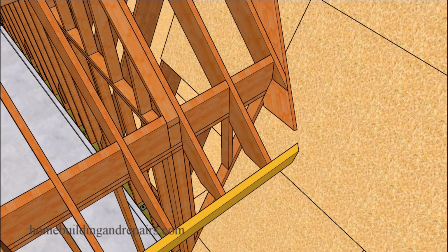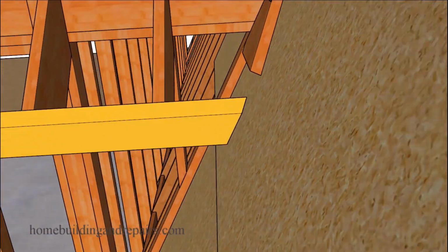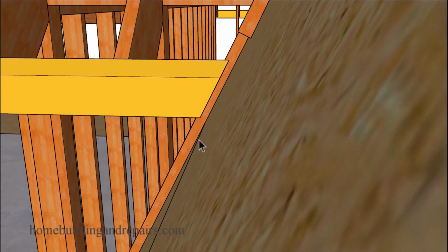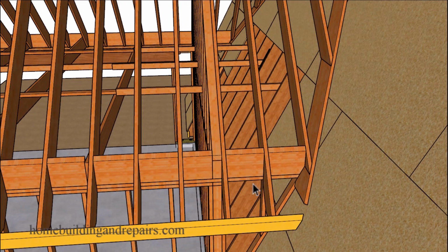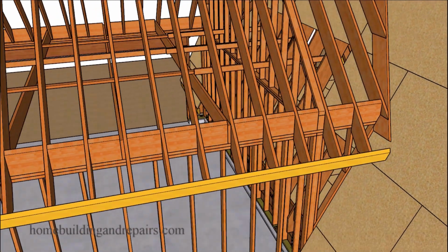And let's go ahead and take a look at the gap between the bottom of the fascia board and the sheathing. This will allow us to install roofing materials underneath this section of the roof. And this might require you to leave some of the sheathing off so that the roofer can install the roofing materials underneath this area here. It's going to be a little more difficult to do if you have the sheathing attached. A lot of times we'll just leave a board. We'll have a piece of the sheathing that might be this big here, cut separately so that the roofer can remove this section, install their roofing, and then reattach the sheathing, nail it off, and then install their new roofing materials over this section. And I don't know if I have a video on that.